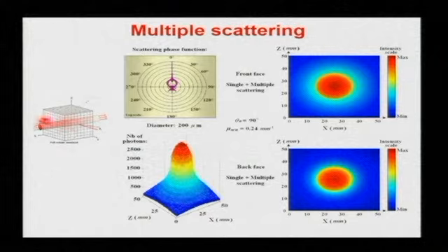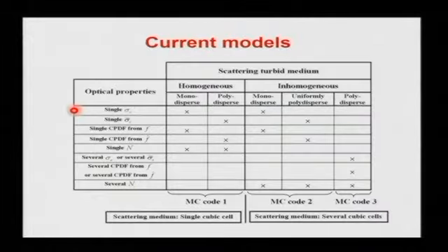And the question is, okay, how correctly am I able to fill this medium and what can I do? And you see, we're able to prescribe homogeneous or inhomogeneous medium with monodispersed particles, polydispersed, or let's say uniformly polydispersed, or the combination. And for that, we clearly need to change the model. So we started, let's say, from the simple one, like for homogeneous medium. Then we developed others and others, where we're able to consider different distributions of particles within the medium.